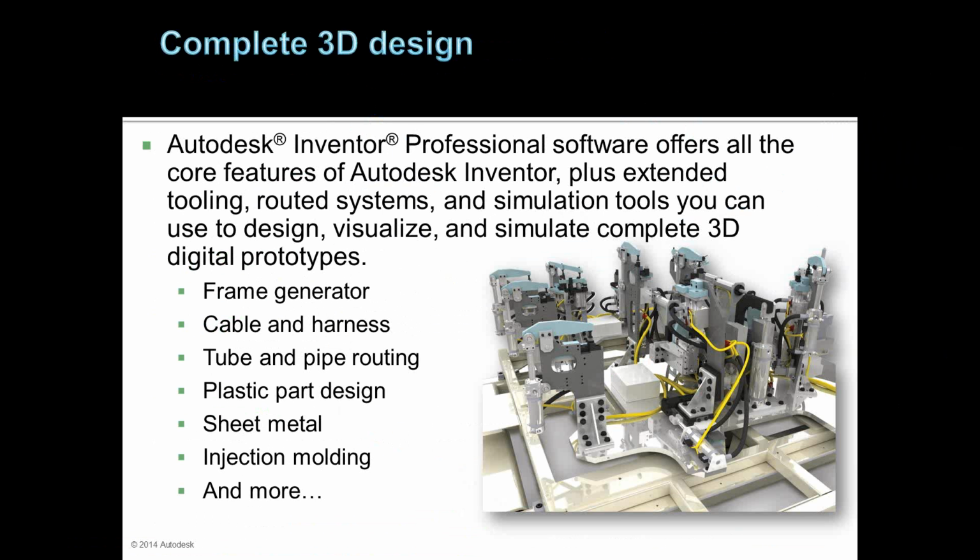You also have the cable and harness routing system in the professional module. That allows you to do point-to-point cable and wire routing, and you can map those or route those to a harness in a 3D environment. So when you do that, now you're given a cut length of the wire. You know exactly how long that wire needs to be to go from point A, run around this pole and through this harness and over this hump and around that fan and connect to point B. You can get that length from that 3D environment.